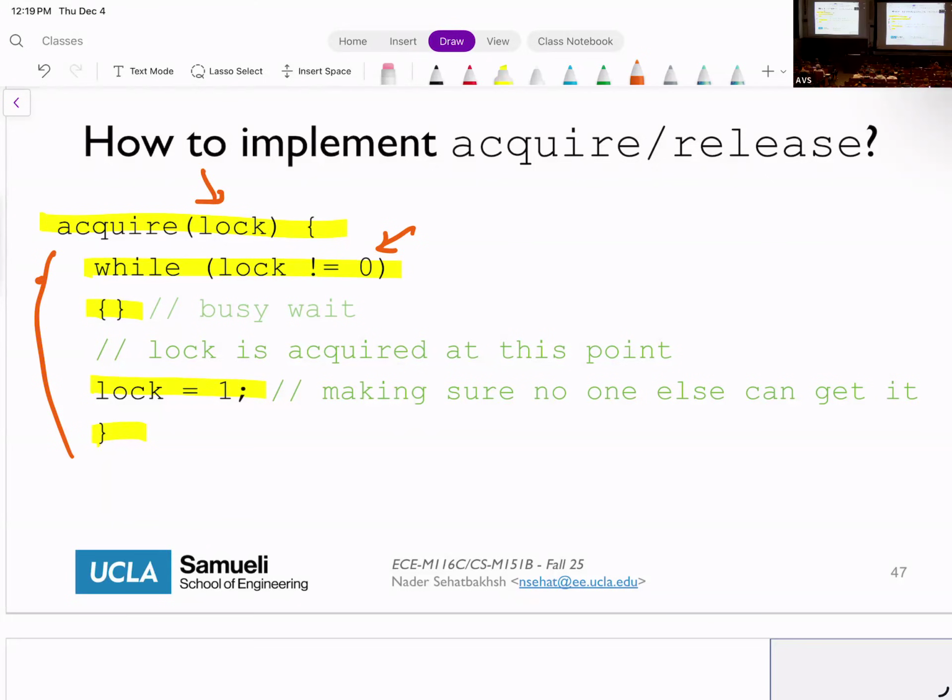Okay, so the implementation of a lock is very important to be efficient, because essentially what it does is stall the processor, right? The processor waits and waits until the lock becomes available. Sometimes this leads to what we call deadlocks, where nobody releases the lock, one core always stays and the other core is also waiting for it. So if there is some form of circular behavior, you're going to have problems.